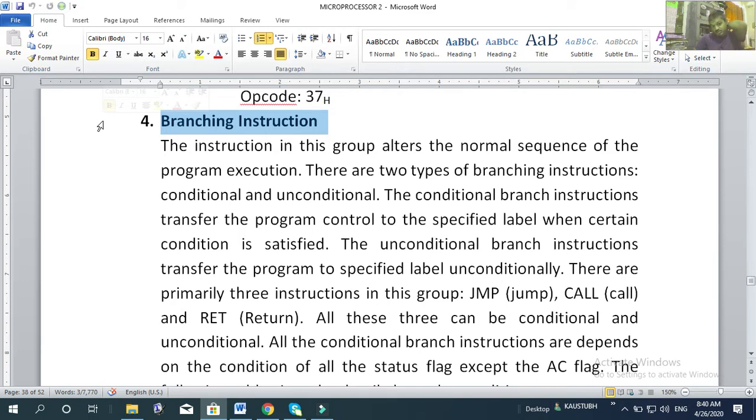In the case of an 8085 assembly level program, you have written your program in memory. Memory means the ROM or RAM. ROM is read only, where the monitor programs are stored, and your user programs are written in the RAM. In a particular block of RAM, in sequential locations, you have written your program.